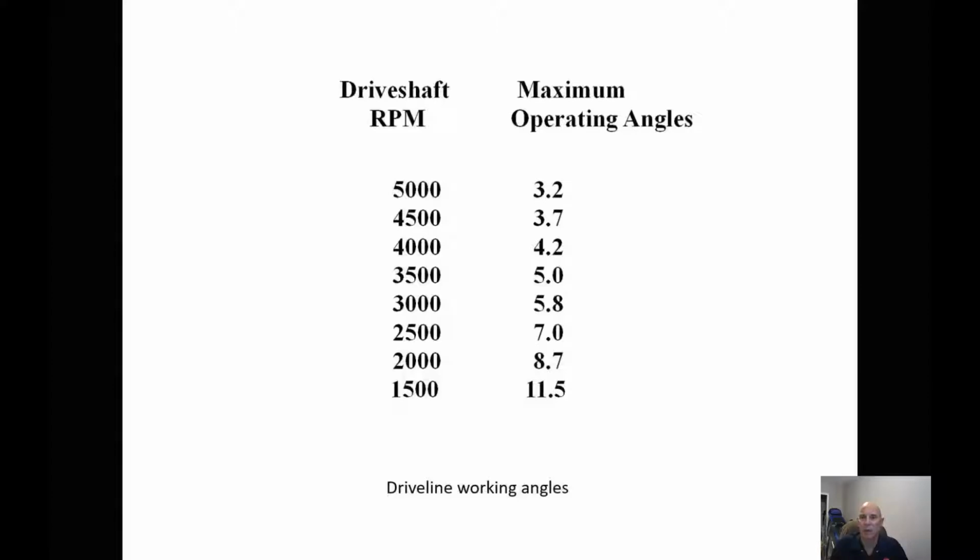One of the big problems is a driver forgets to raise his airbags after leaving the loading dock. What happens then is it changes the angle of the front and the rear diff. It tilts them forward, which increases the angle of the driveline, and it'll cause a vibration.